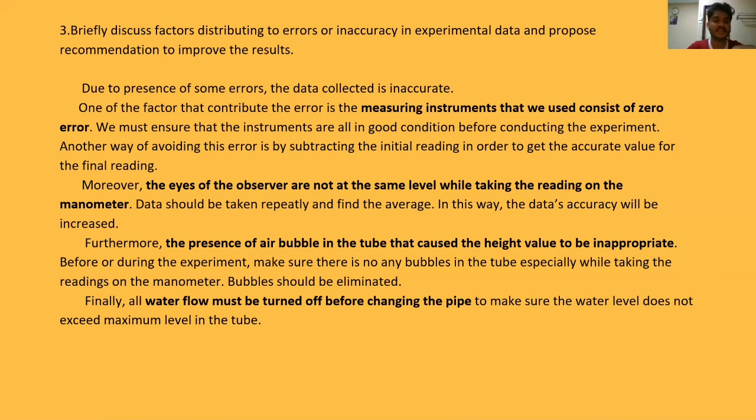Furthermore, the presence of air bubbles in the tube causes the height value to be inappropriate. Before or during the experiment, make sure that there's no air bubble in the tube, especially while taking the reading on the manometer. Bubbles should be eliminated. As I told previously, air bubbles will affect the height of the pressure.